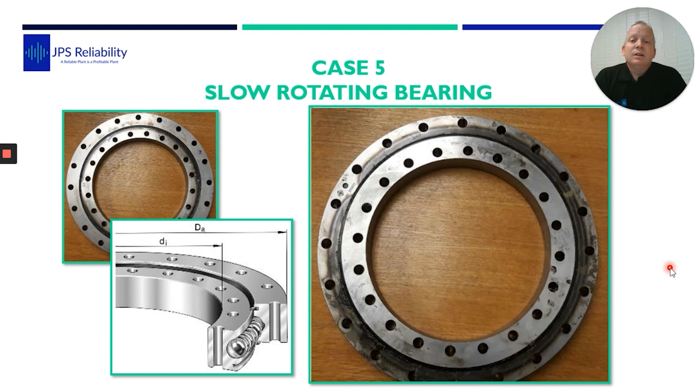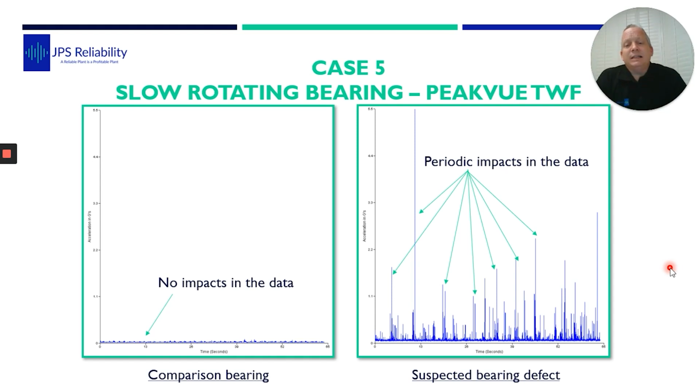There were lots of doubting Thomases on whether we can actually pick up a defect with vibration analysis because it's going so slow. But at the high frequencies where we're sampling, you're getting into the ultrasonic range anyway. This was our first data. So we chose PeakVue and we were using the time waveform, and we were sampling really high.